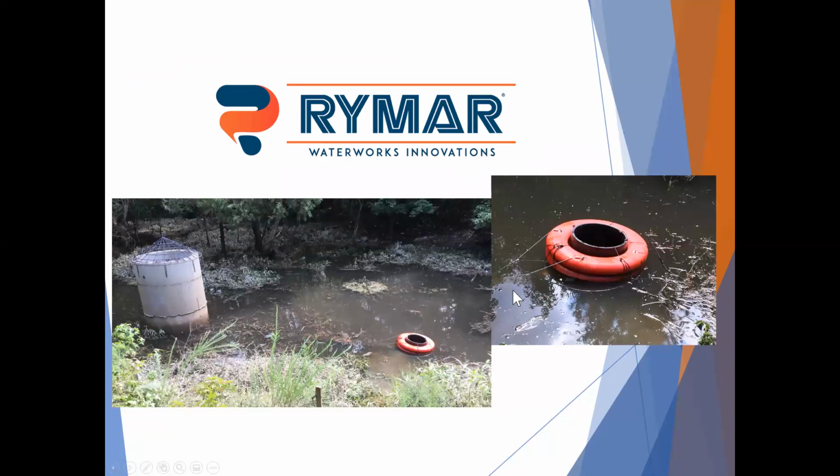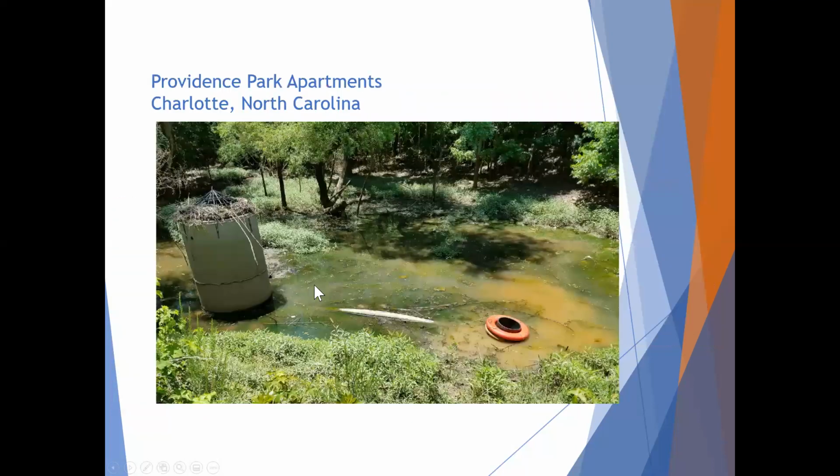This was our older model skimmer that was in place. Again, it was a live stream area, so when it would rain, it would take a little while to drain down. With some big rains, water got up to the top of the riser and had a lot of trash. We had to keep that cleaned off. One thing we noticed was that we put in an HDPE pipe between the skimmer and the riser, and over time that pipe bowed. This is probably 3 years after the skimmer had been in place. You see a bow in here from the HDPE. When it gets warmer, it bows.